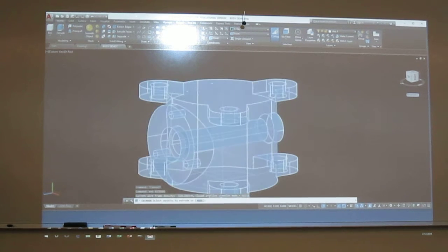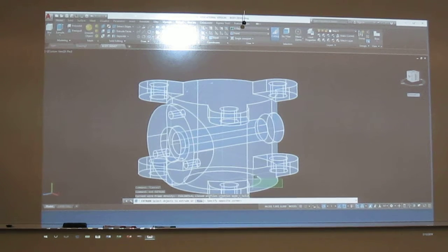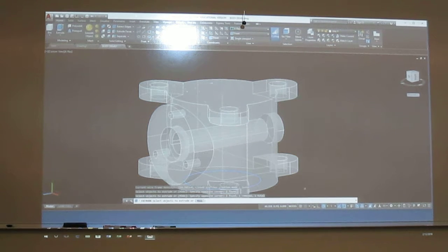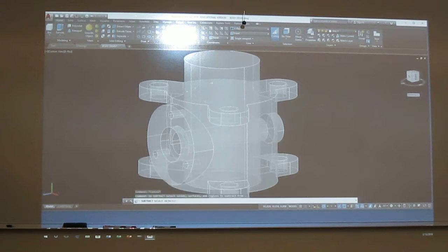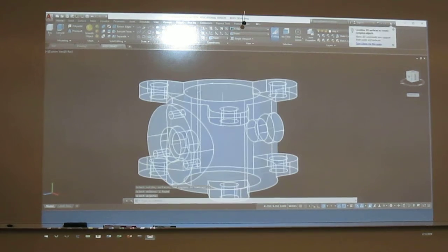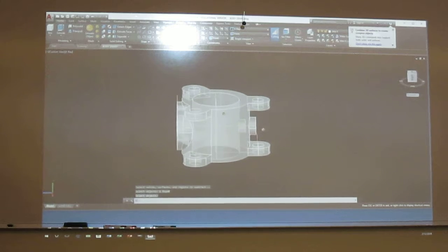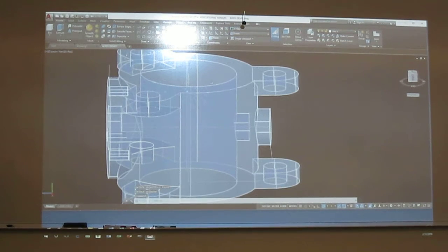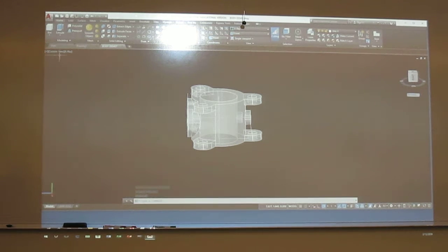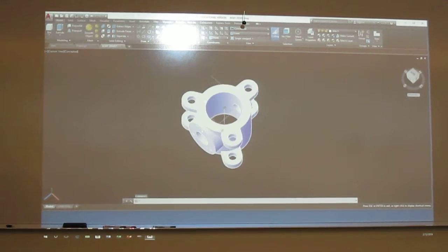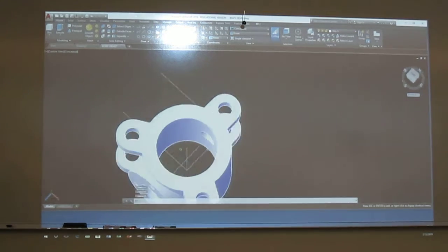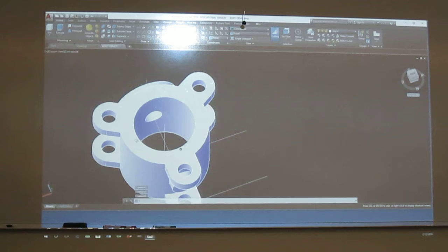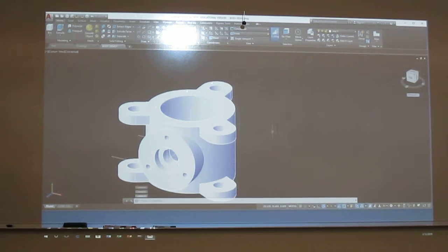Now we still have the collar to do, the hole through the middle, so let me do that. I'm going to extrude on this shape down here, and I'll just select all of that, deselect my model, leaves me my hole, and we'll shoot that guy up to there. Let's subtract from this. Okay. Now this guy's pretty much done, and you can kind of see where that hole for the shaft comes in right there. Okay. Then we go to conceptual. One second, Lisa. Okay, so we go to conceptual, and it creates all those shapes for you. Like these ellipses back here, that's all created for you from this solid Boolean process. And this guy's now done.